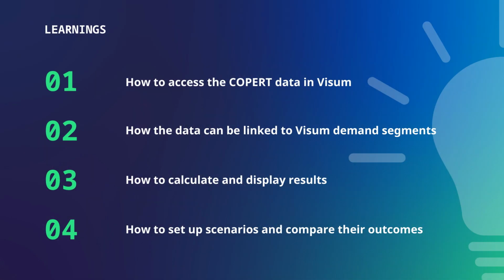Before ending the session, I would like to summarize the learnings from today's session. You have learned what COPERT is. You have learned how emissions can be calculated using COPERT in Visum. You have learned how you can use the data structures from COPERT in Visum to calculate emissions for fleet compositions that consist of user-defined data. And you have also learned how to compare scenarios with respect to COPERT output.